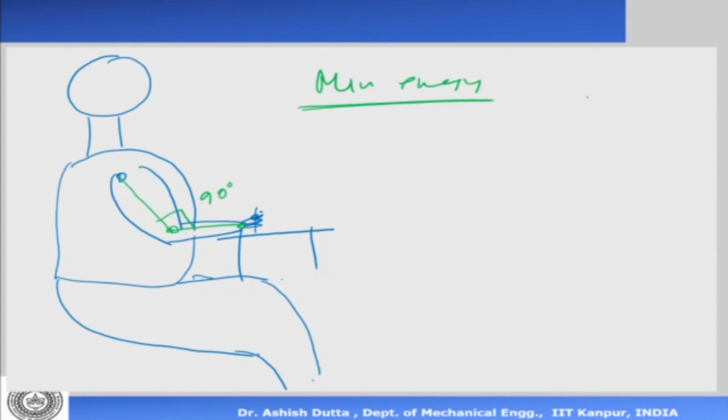Okay, so it is not only that we are studying robotics and we are talking of mechanisms and things like that, but this is valid even for us, because in our legs, hands, arms, body, we are also linkages, right? So whatever we are studying is valid for us also. So minimum energy, we have seen, you can ensure by maximizing the determinant of J. That's very, very interesting and very important for us, because we are always interested in finding paths where your energy gets minimized.